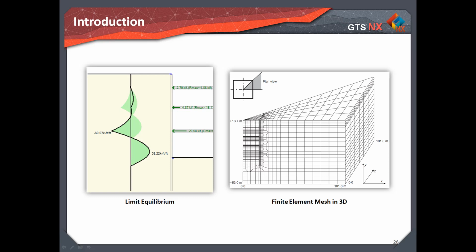Technically, full numerical analysis is the only method that satisfies all the theoretical requirements discussed earlier. It allows for realistic soil constitutive models, incorporates actual boundary conditions, represents the soil behavior with the correct geometry, and allows for modeling the initial stress state, construction process and soil structure interaction, consolidation analysis, and so on.